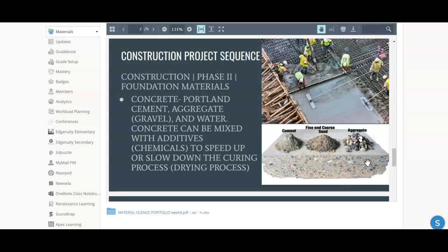So they'll mix in chemicals to literally bake the concrete dry of all water. You can think of places like Chicago or New York where it snows, and if it's too cold, the water's not going to evaporate from the concrete. And inversely, on the flip side, you'll have chemicals that slow down the curing process, the drying process.